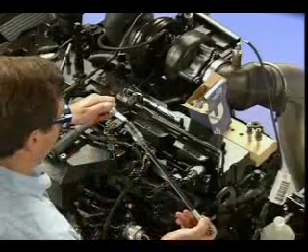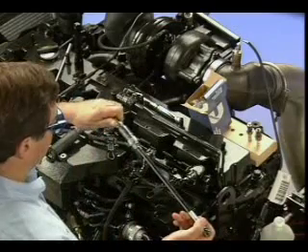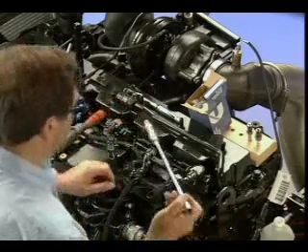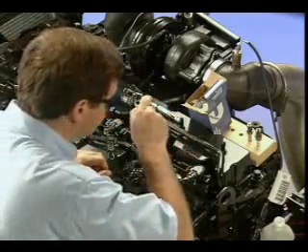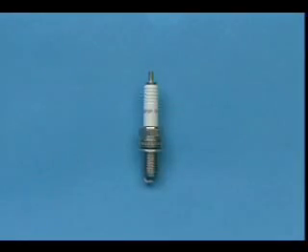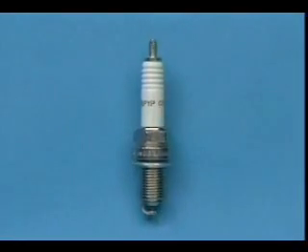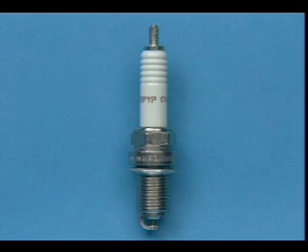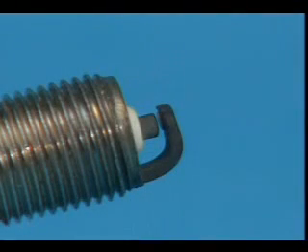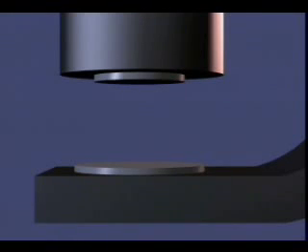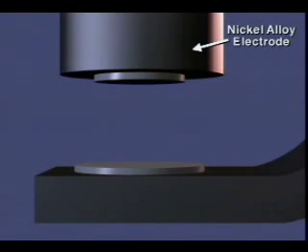A spark plug is installed for each of the 6 cylinders in the spark plug bores in the cylinder head. The spark plug design and its condition are critical to engine performance. Because of the extreme conditions in which it operates, the spark plug used for the Cummins C8.3250G is not a standard automotive type plug. The plug utilizes a nickel alloy electrode.